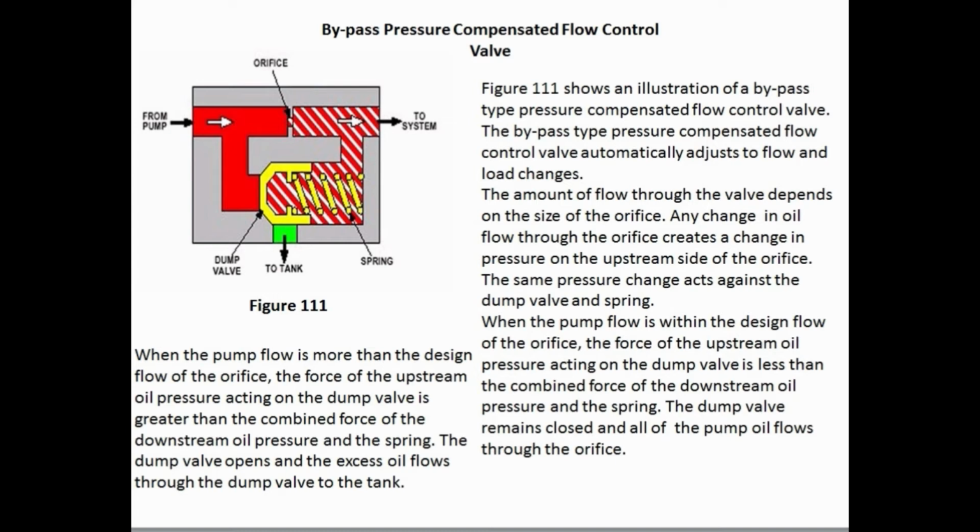When the pump flow is more than the desired flow of the orifice, the force of the upstream oil pressure acting on the dump valve is greater than the combined force of the downstream oil pressure and the spring. The dump valve opens and the excess oil flows through the dump valve to the tank.